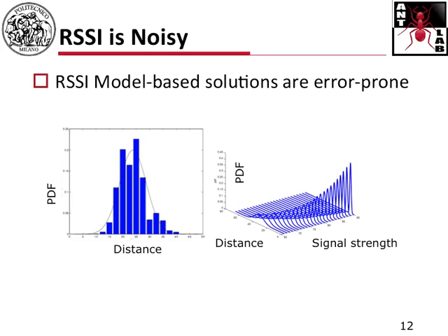To summarize, the received power does not depend only on the transmitted power, which is the underlying assumption of that model which I showed you yesterday, but some external noise factor can kick in. And the more this noise increases, the wider this bell-shaped function is, which means the farther away you can be from the real value of distance which you have to measure. Clear?